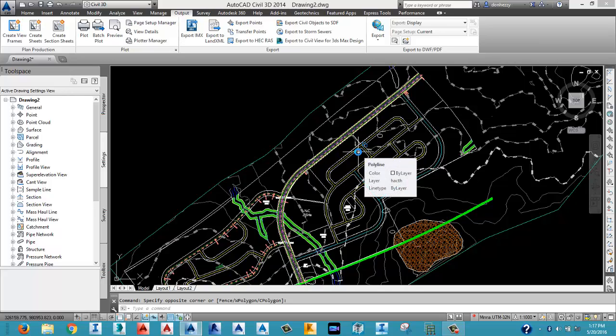A view frame segments our road length into subsections for better outputting or presentation, because your full road length can't be on just a single sheet. So they came up with something like, let's create a segment for maybe 0 to 100 meters, 500 then to 1000 meters, in that interval, or you run it in any interval based on the scale of the paper.